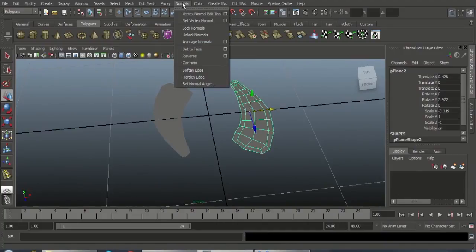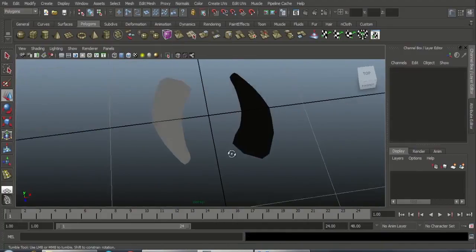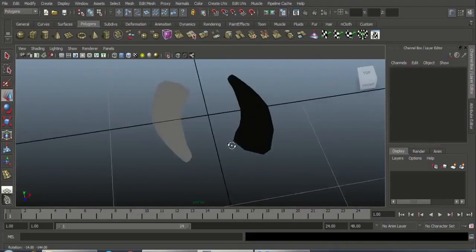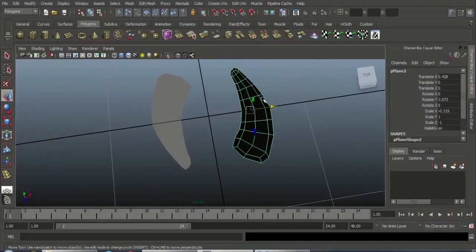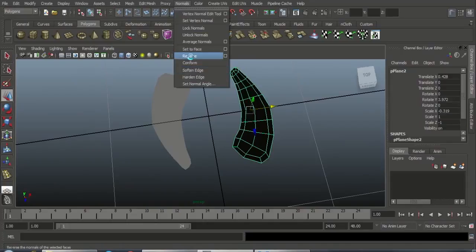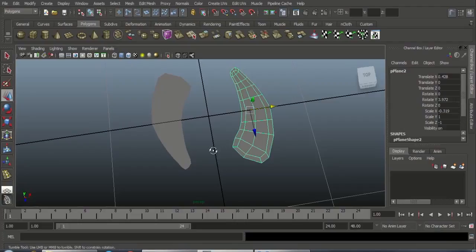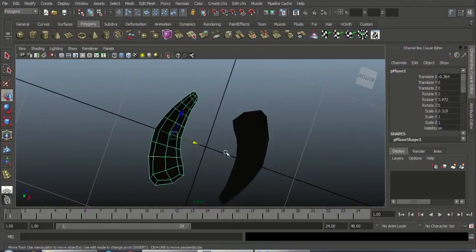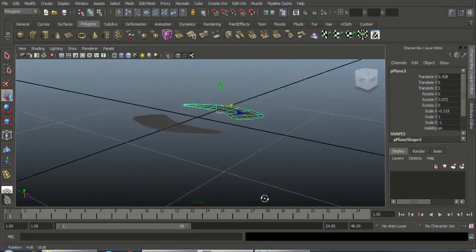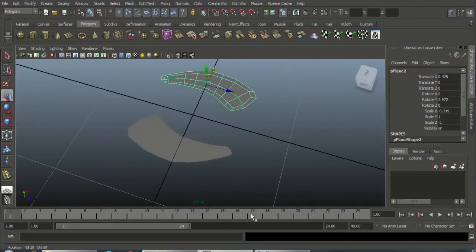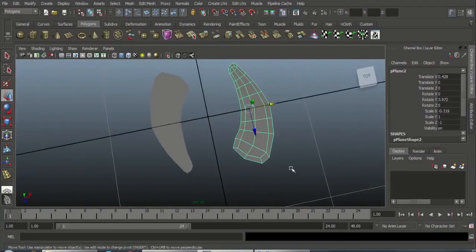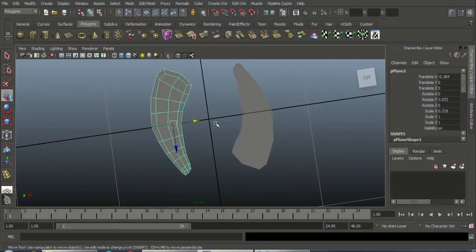See, when I go to normals, I will change it to reverse. So that means the light is reversed. Sometimes it will happen like this, so that means you want to flip the normals. Select this one, go to normals and choose reverse. You want to see that the mesh's both sides are the same. Here both sides are the same, black. So that means the light is on the top side. Okay.